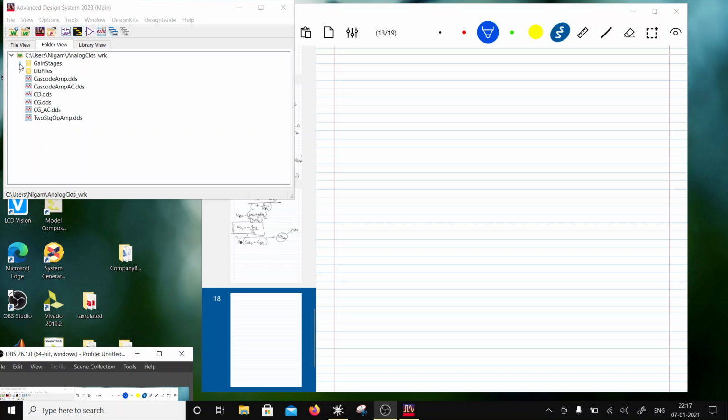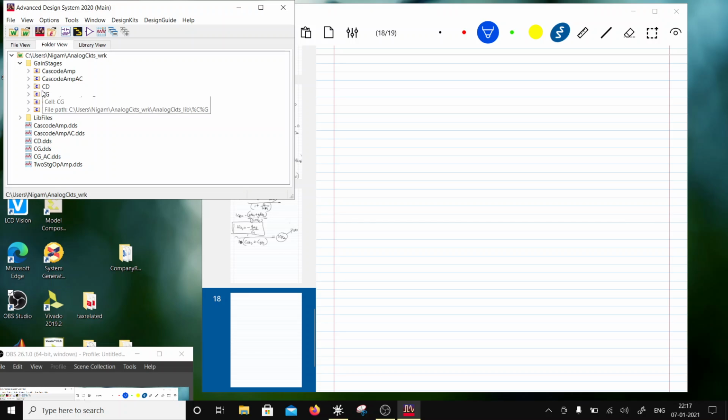This is Anurag Nigam. Last time I demonstrated the high frequency response of a common source amplifier, and we concluded that in a common source amplifier we are looking at two poles and a right half plane zero. Then we used a compensation technique to move that zero first to infinity and then to a point in the left half of the S plane. To stabilize it, we introduce that zero between the first pole and the second pole.